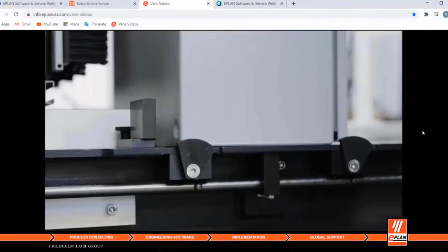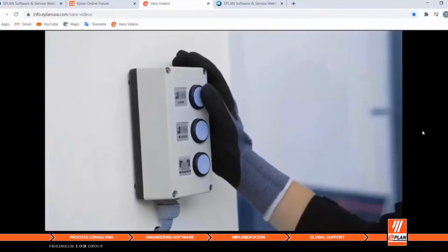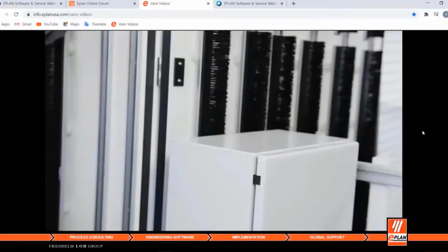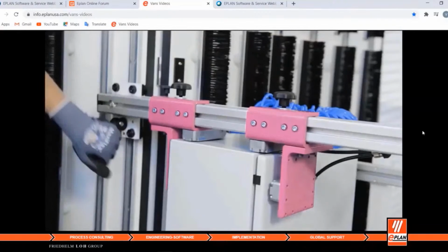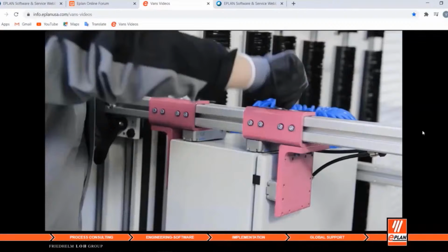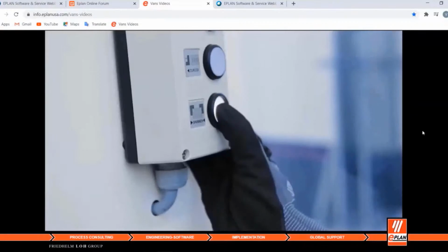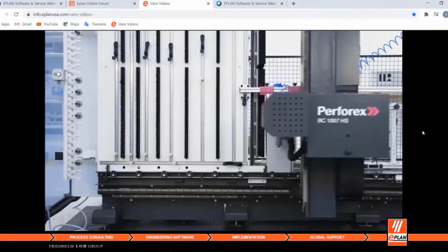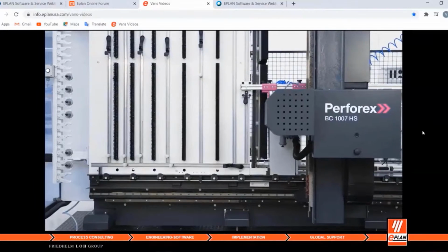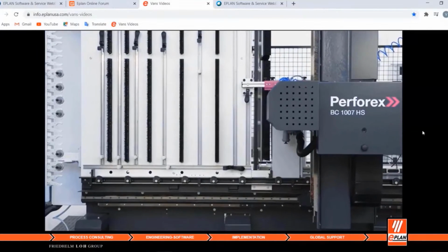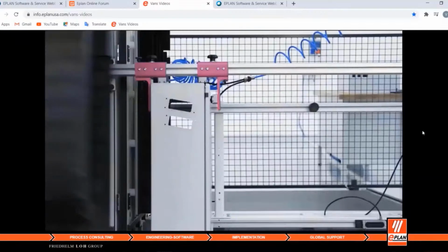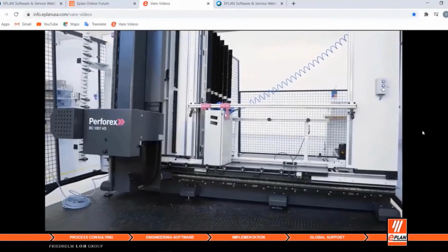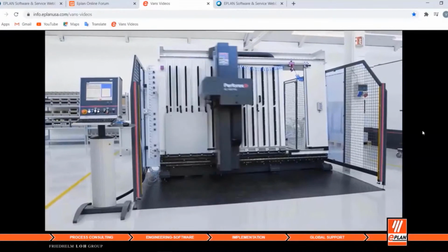And so the 0 points on the machine are hard mechanical 0 points, and we see the motorized depth and control bringing the workpiece up to the 0 point in the Z-axis. Here, all of the clamping systems are very simple and easy to use. So we use Festo pneumatics to really grab onto that workpiece and hold it stable during the machining process. So I think that gives you a pretty good overview of what the machine is doing. And of course, that enclosure can be rotated to work on any further sides that are needed.